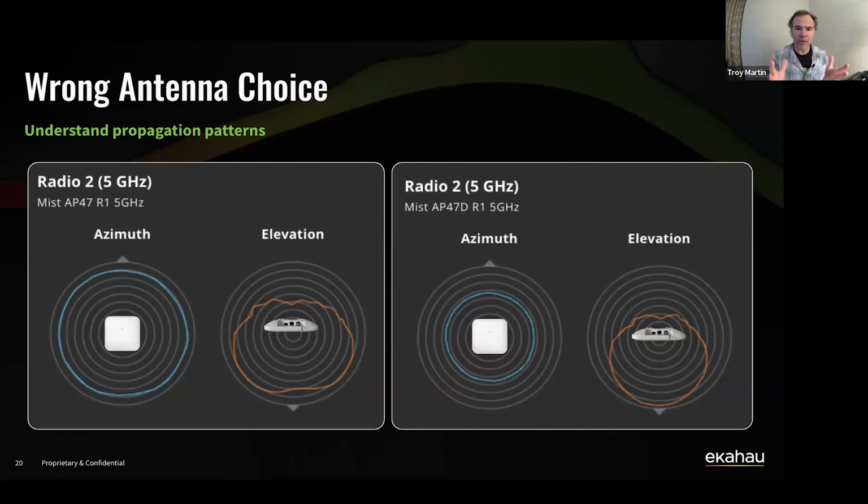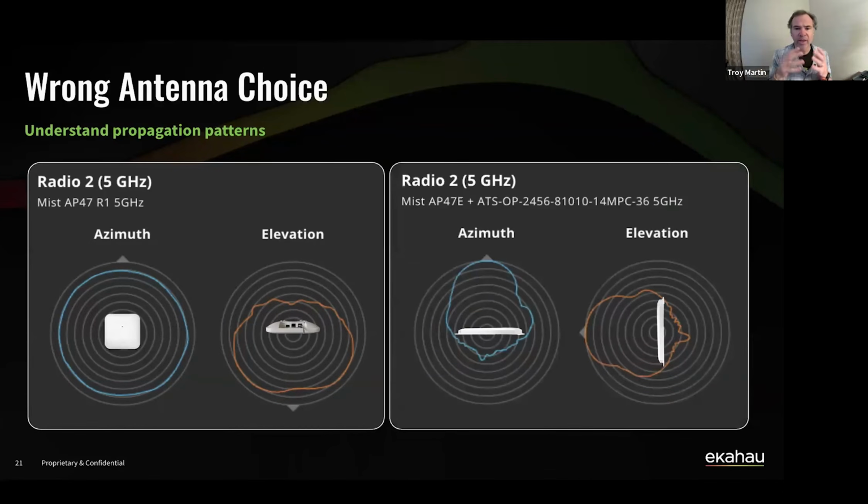Which is a good approach. And that's the reason that a lot of those integrated omnidirectional antennas make a lot of sense to go on the ceiling, right? And there's a big push to have them in that orientation. You can reach out to vendors of different manufacturing brackets where you can get little 90-degree arms that stick out from the wall. So that AP that we had that was missing its antennas in the auditorium, you can get a little right angle bracket, mount that access point to that bracket so that it's oriented as if it was mounted on the ceiling, although it's very close to a wall and it's not 40 feet or 15 meters or something crazy way up in the air, right?